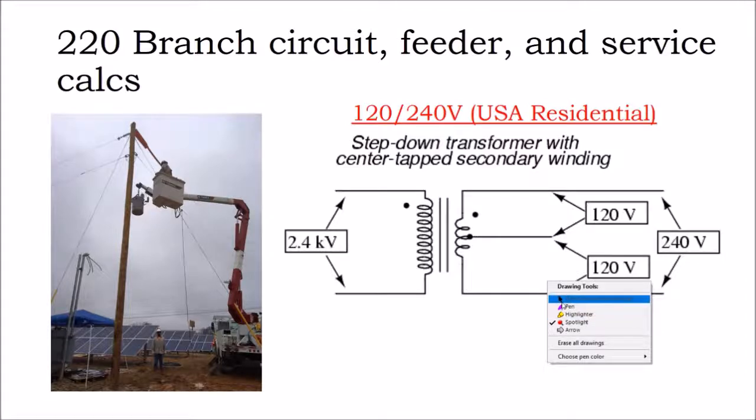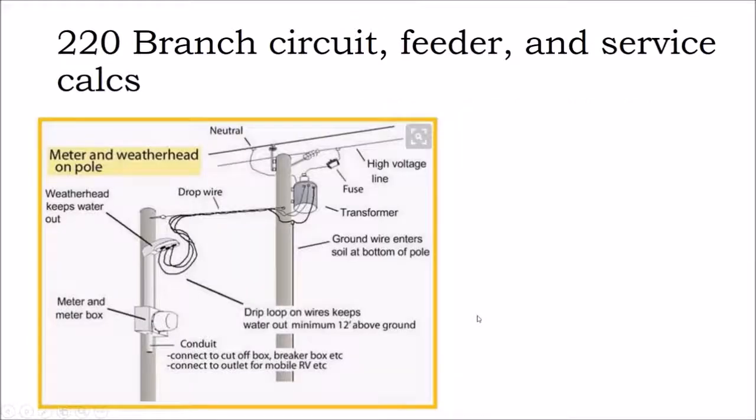Now, in our home, we have single pole breakers that are 120 volt circuits, and then we have double pole breakers that occupy 2 breaker slots, and those are for our higher voltage appliances. Maybe your dryer circuit is on a 240 volt device. Maybe a deep freeze might be on a 240 volt device. It'll just be designed for a little bit more powerful electricity, electricity that operates at a little bit higher pressure and can push more electrons through a conductor than a 120 volt circuit can.